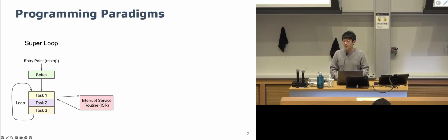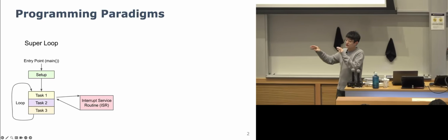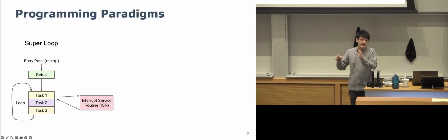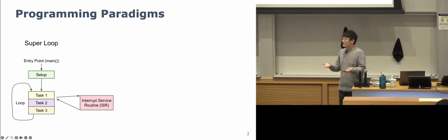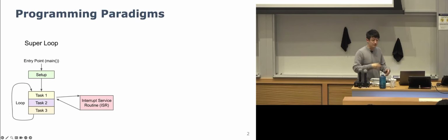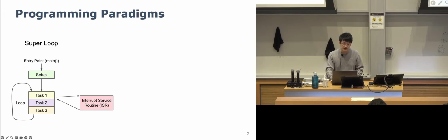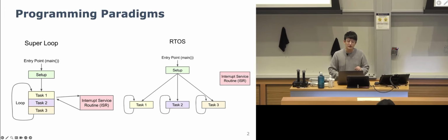But when we talked about this, there were already questions in the class. What if we need to run a much bigger block of code within this big loop, and those things have their own schedule? How do we deal with that? The normal peripheral interrupts will likely be unable to handle that. So the way we do it is through what's called an RTOS.